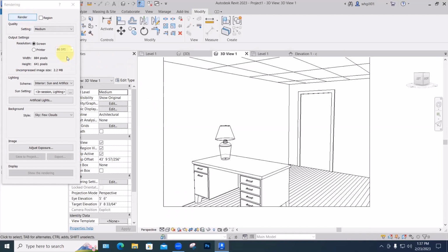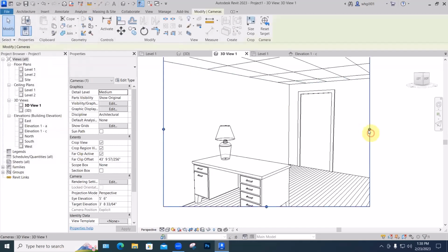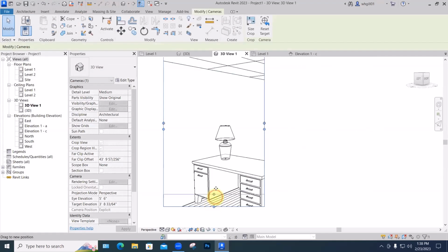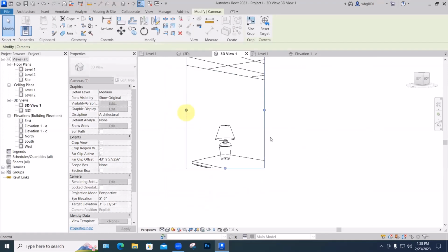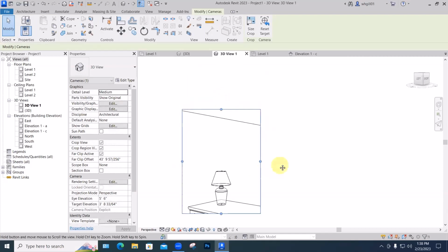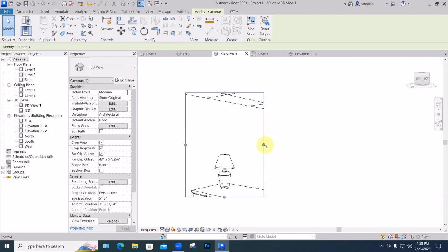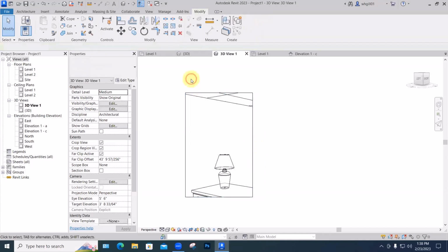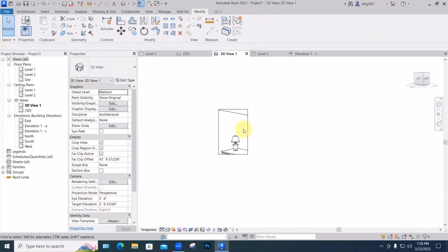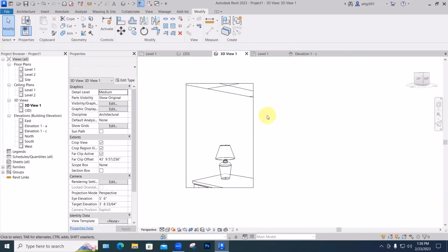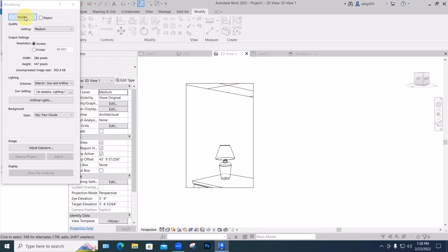Oh, it's worth mentioning right now that I'm rendering two times a minute or something or other. And the more pixels you have to render, the longer it takes. Just a linear thing. So I think what I'll do here, just to make this all go as fast as possible, is crop this down to only the part that I'm interested in, which is desk, wall, ceiling, and lamp. And also the size of that matters. This will take a lot less time to render than this will. But we need to be able to see it.